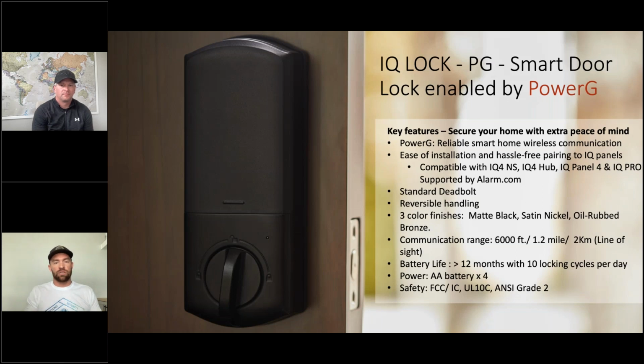The other cool thing about this is just how much easier it is to learn into the system. With the Z-Wave door lock, you have to learn it in so close to the panel. You have to allow that secure enrollment to go, right? You kind of have to pull the lock apart and get to the pair button. Some locks are different, some are in the menu. This lock pairs in very easily, very quickly. You put the panel into auto learn, same place you'd go to learn in a door sensor or a motion detector. You pop the batteries in this door lock and it learns in very quickly. And you can do this at location. So I can do this in my detached garage, without having to worry about doing it 3 to 5 feet away from the panel. So it installs very easily, has awesome range, and is definitely quicker than pairing a Z-Wave lock.